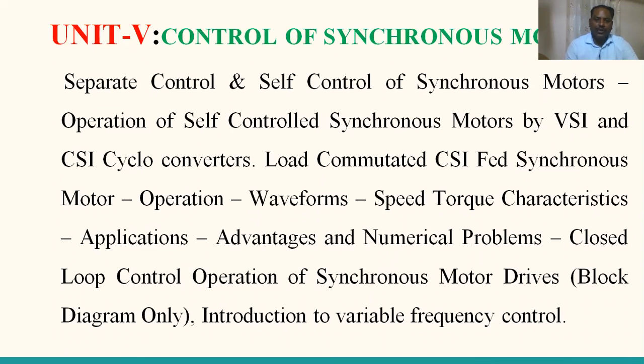Here also, speed control is possible only on the stator side, either voltage control or frequency control. Voltage and frequency control are achieved with the help of voltage source inverters, cycloconverters, or current source inverters.